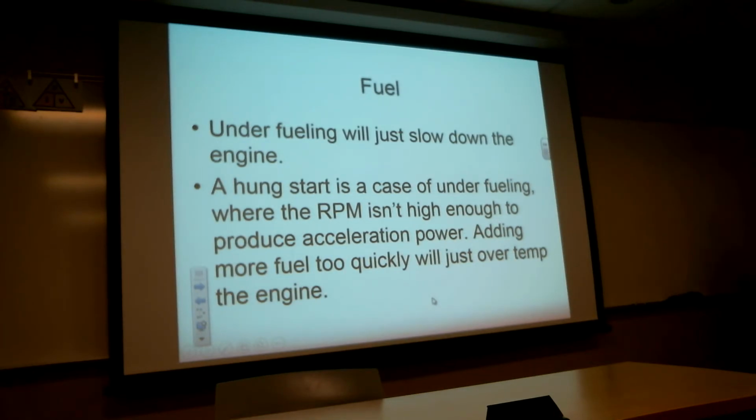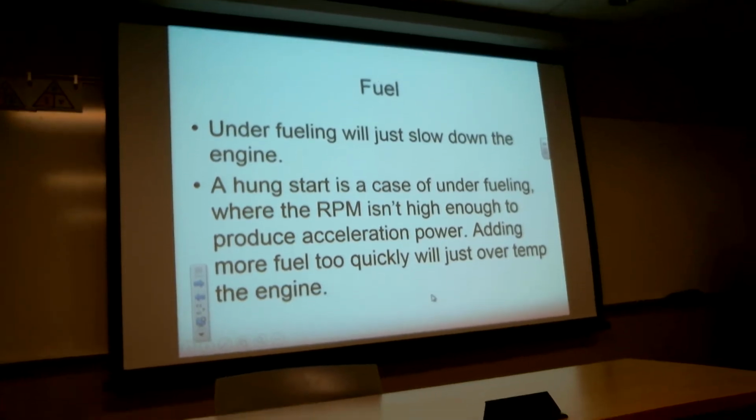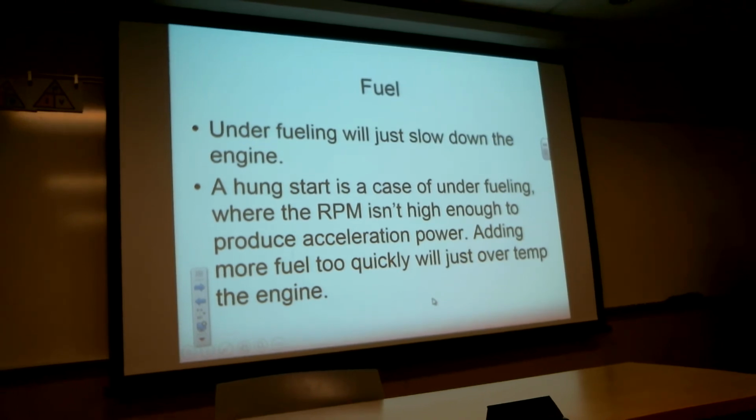Okay, so underfueling is just going to slow down the engine. It won't pick up any speed if it doesn't have enough fuel. It's just a weak mixture, a very lean mixture. A hung start is a case where an engine doesn't want to accelerate, and grabbing the throttle is not going to help it, because then you're not moving enough air through the engine. If you add extra fuel without enough air, now you've gone rich again and you're overfueling. So you've gone from one extreme to the other.